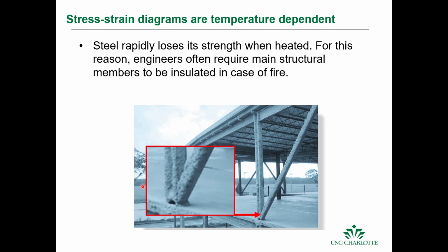Another thing to keep in mind is that steel loses its strength significantly when heated. That's why if you look at structural members for buildings, you'll often see them coated with some form of thermal protection, just to make sure that the strength of the material is preserved in the event of a fire. Okay.